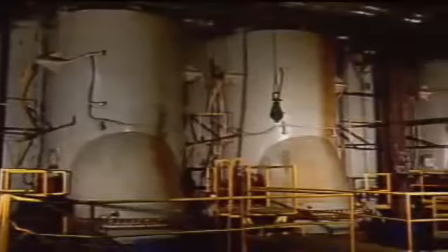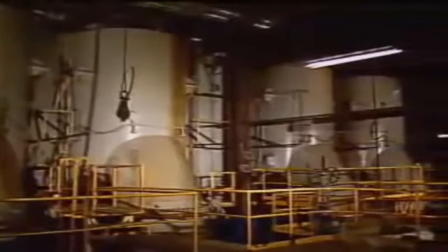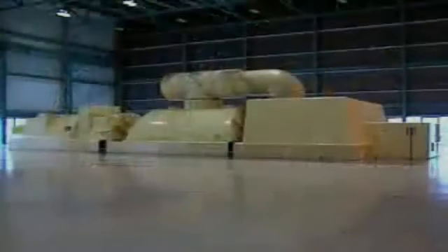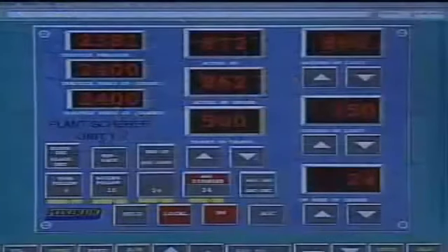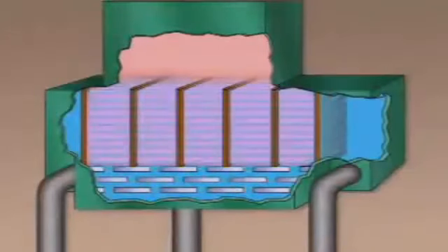The two-halved design allows half of the condenser to be shut down, while the other half continues to operate. For instance, if there is a severe tube leak or blockage in one half of the condenser, that half can be shut down for repairs, while the other half remains in service. That way, the turbine can continue to operate while the condenser is being repaired. Keep in mind, though, that load may have to be reduced during the repair since condenser capacity is less than before.